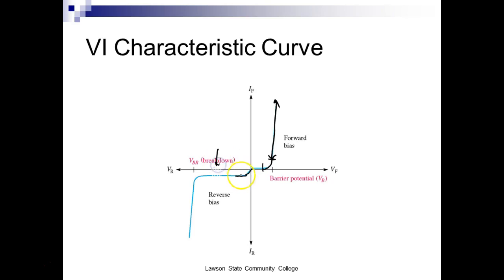they show dots here. When we reverse bias this thing, eventually it's going to do what? It's going to break over. And it's usually a real high voltage, like 50 volts, 100 volts, 200 volts. It's a real high voltage because these things are designed to run as rectifiers, right? Or small signal diodes. But what we notice is that when it does break over, it maintains a fairly constant voltage across it. It just burns up. We can't see it because it does that almost instantly. It burns up. Are we okay?